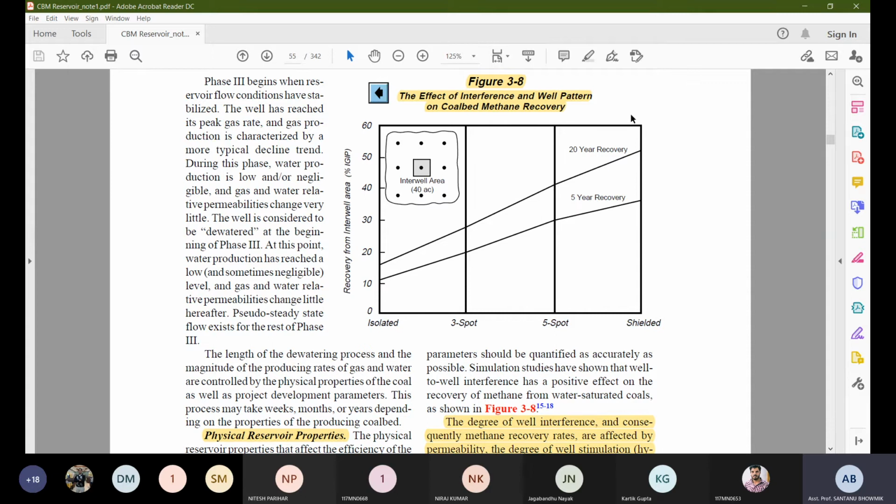So it may happen that for 2 consecutive boreholes, if you are considering borehole 1, 3 times of the diameter on the right side, and for the second borehole 3 to 4 times of the diameter to the left side, you may find that the zone of influence may superimpose, may overlap. It may also happen that they don't touch or overlap one another. In that case, the separation of the boreholes is going to be important. And as your strength parameter is going to vary, this production parameter is also going to vary.